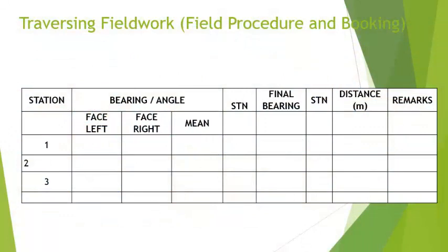The fieldwork of traverse and booking is pretty simple and repetitive until the traverse ends or finishes. On the left hand side is the standard booking form, which consists of many columns. The first column from the left is for the codes or survey stations. As you can see in the example, there are numbers 1, 2 and 3 arranged to the right and left side of the column.